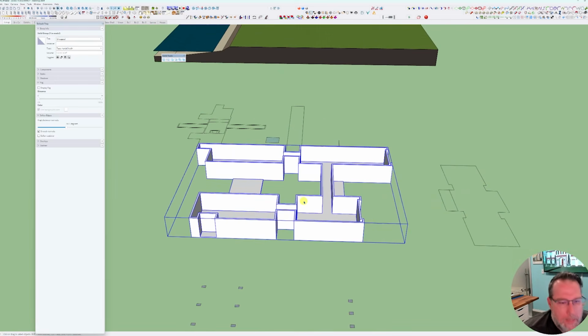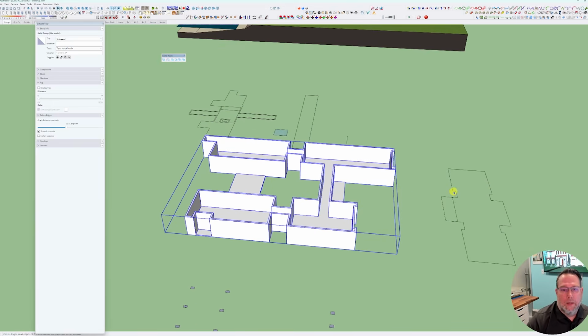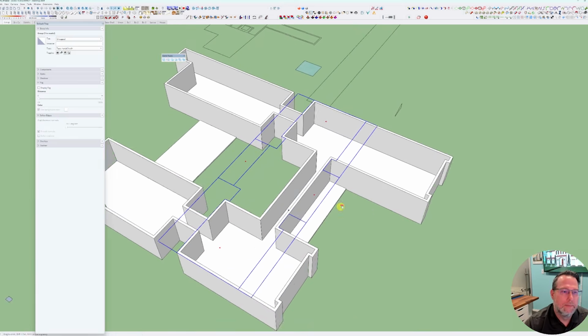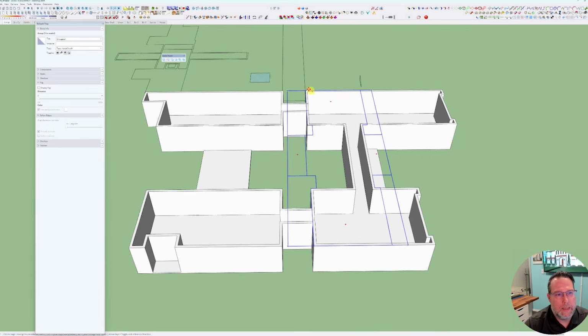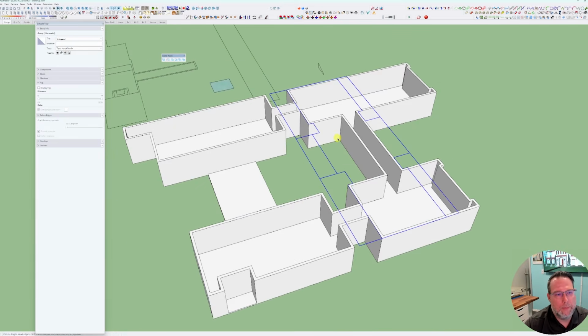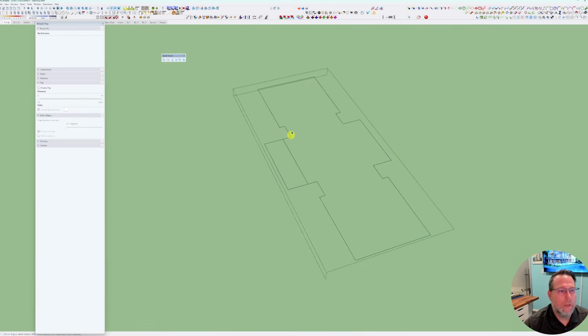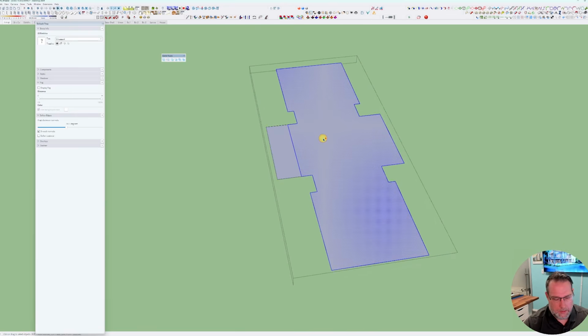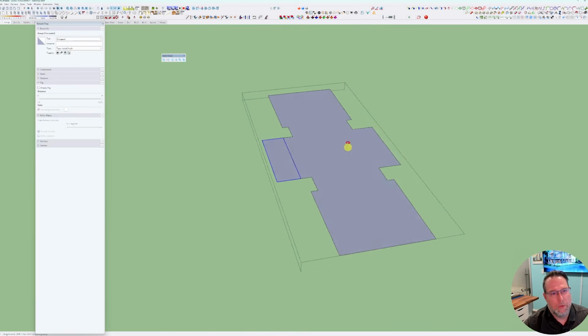All right, so let's create a second floor, which is what I have here. So I'm going to just move this guy up and inference it to the top of this wall, and I'm going to move this over, I believe it's 100 feet that I had it placed. So you'll see that this kind of fits perfectly over top of here. And we're going to do the same thing again. I'm going to select everything, and hit the plus sign to make all my faces. I'm going to turn this into a group and this into a group.